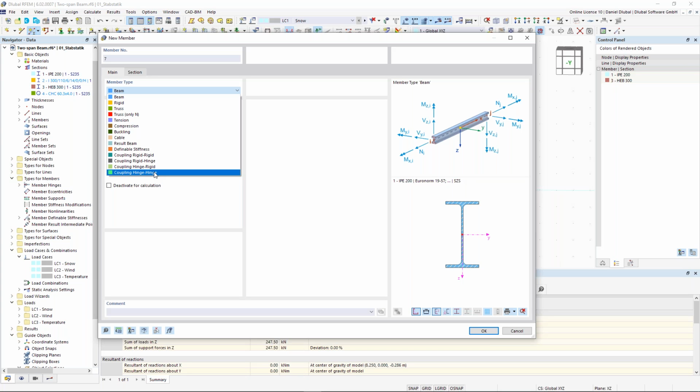But this is not an easy task for a structural engineer who is more familiar with the consideration of existing structures. In general, as a structural engineer, I would first calculate the existing structure, and then in a second step, neglect the existing structure and consider only the newly added structural elements. This would be my approach.